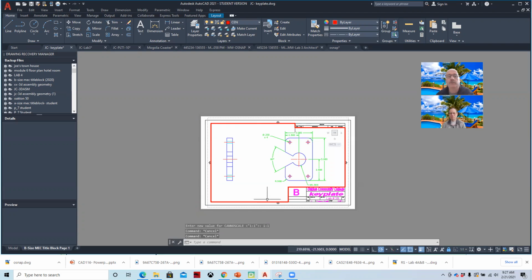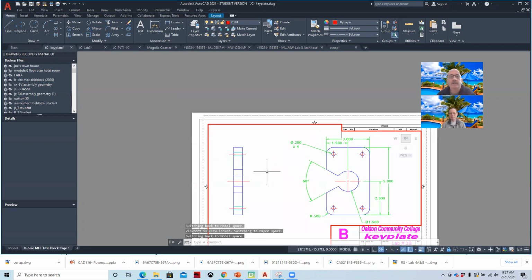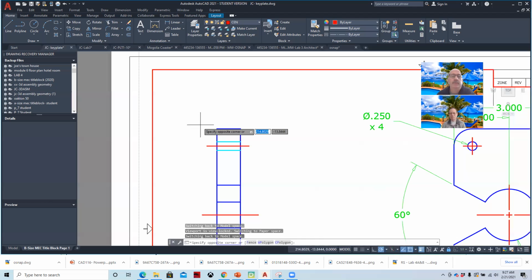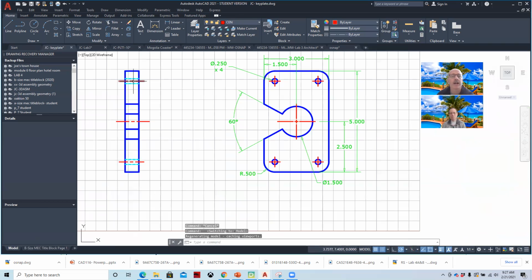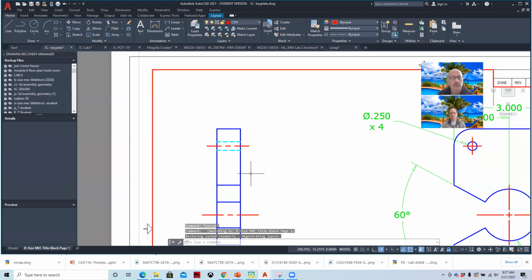This is the way that we would create these geometries. And then everything should line up from view to view. You should also have proper line types and line weights. This can be a bit of an issue where the dim scale and the LT scale don't display properly. So if we type PSLTSCALE and set this to 0 and then regen, it usually fixes it. Just one of those tips and tricks, because in model space it's correct, but when I had that in paper space, without the PSLTSCALE, it was not correct.